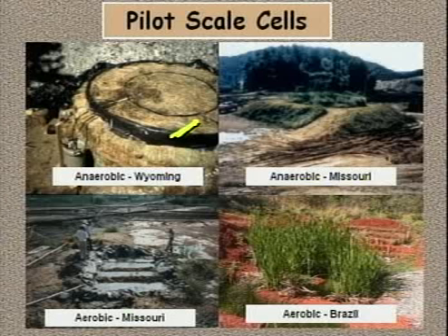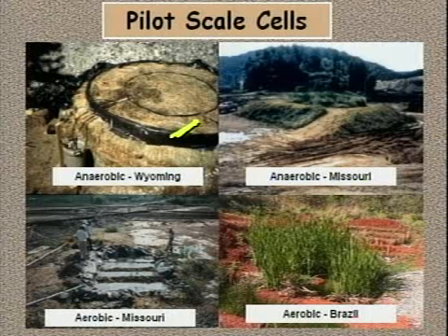The test is typically run for 6 months to a year, but especially through the winter season, because sulfate reduction rates do slow down in the winter, and you need to get a handle on how slow they do slow down.